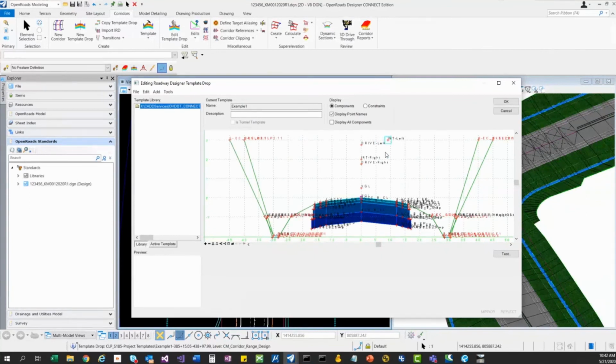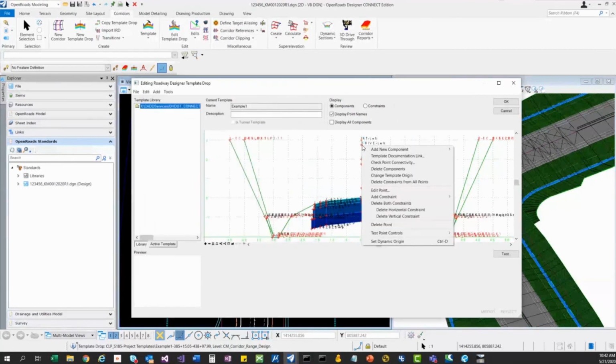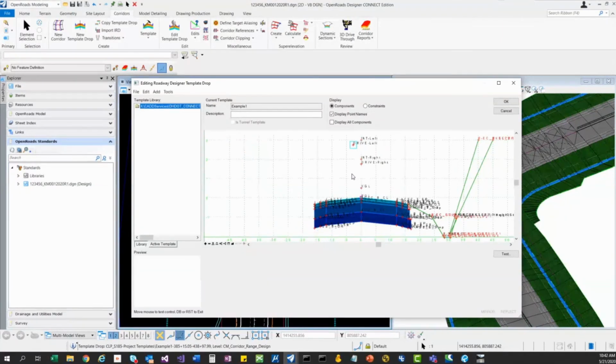Same thing for the intersection right one: if you move this to the right, it just controls the display on the right side. Now we also have driveway left and right, which does something similar. So if I show you that one, in this case, it is just removing the grading and the shoulder steps, but not the actual shoulder.